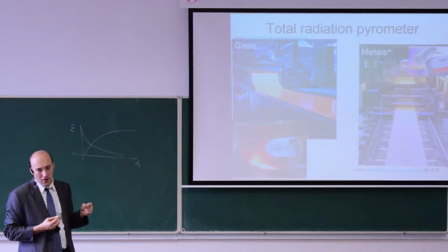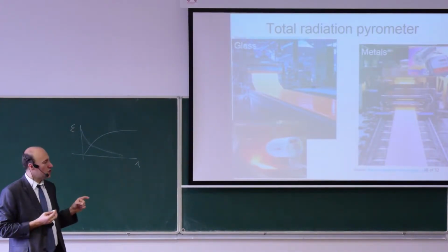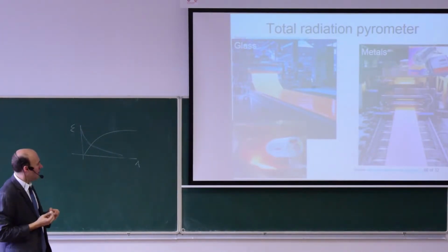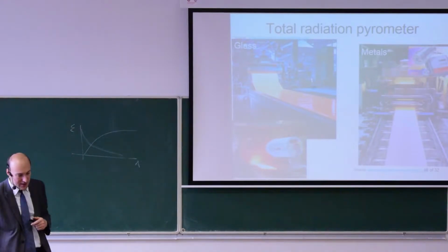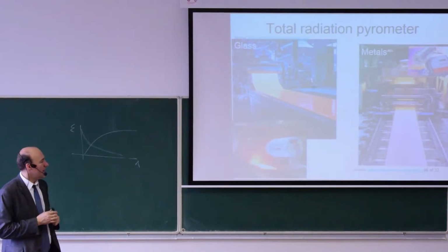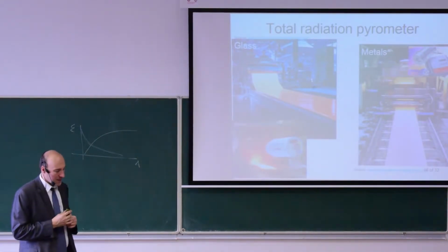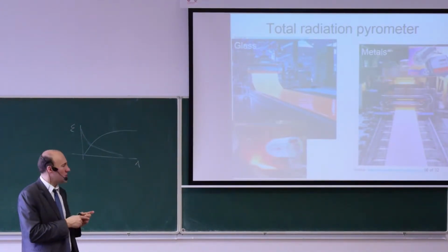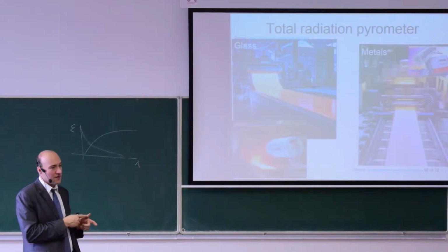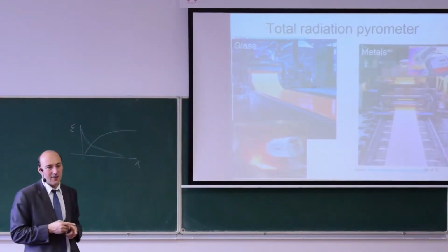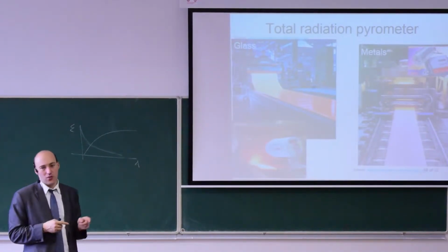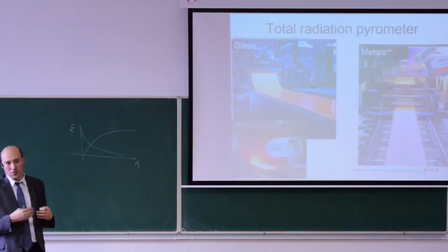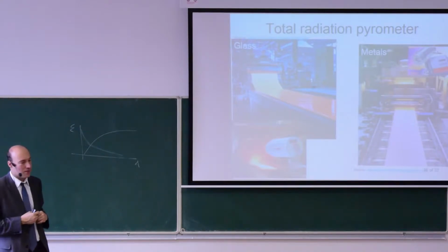So if you are looking for a specific temperature, you should change the emissivity during the measurements. I will not show any specific charts here, but it's quite significant. For example, you measure with emissivity of 0.8, but if the temperature is changing from 1000 Kelvin to 1500, the emissivity may drop from 0.8 to 0.5. And this will give you a different reading in what you get from the non-contact temperature sensor.